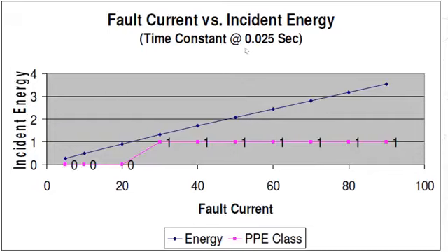You will find that by playing with this time constant, you have already reduced the time level to that particular value at which the incident energy is minimum at that particular location. Now trying to reduce the fault current will not have an impact on the incident energy. For example, if the fault current is around 90 kiloampere, and by a method we reduce that fault current from 90 kiloampere to 20 kiloampere, the incident energy is here around 1 or 1.2 cals per centimeter square. It will have a minimum impact.